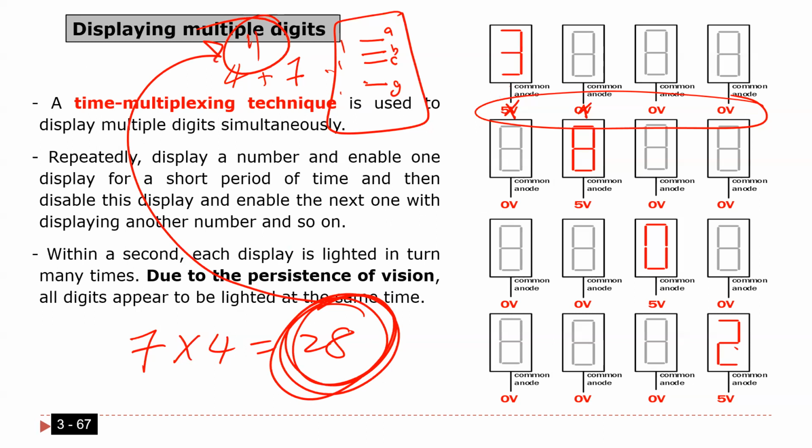Okay, listen to me, for some processors, 11 pins are okay. Especially if I have a big microcontroller with too many pins, like for example 100 pins or so, maybe 11 are okay. So you can just connect it directly to the microcontroller. Sometimes we do that, okay? Here, because this is a small processor, even 11 is a lot.